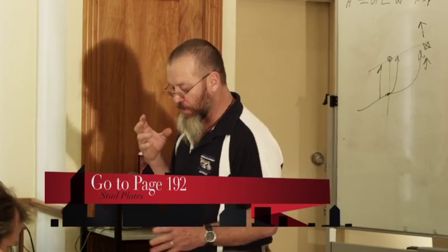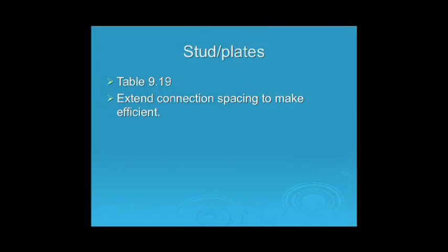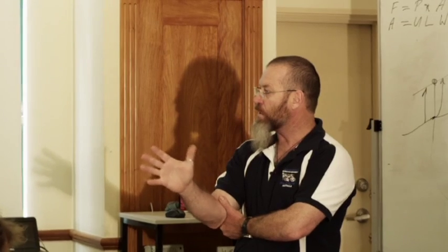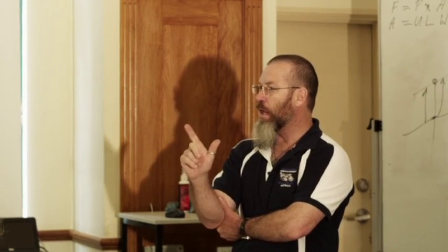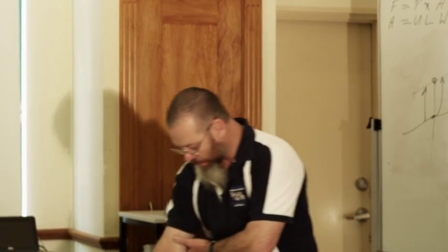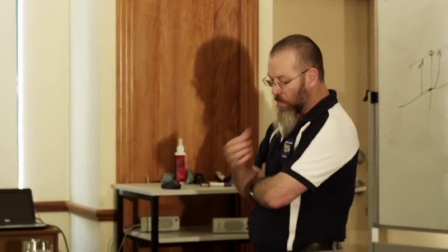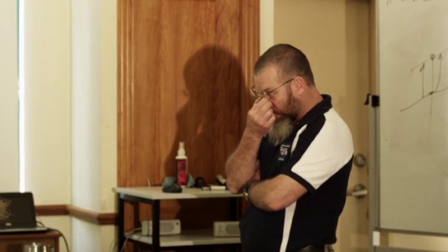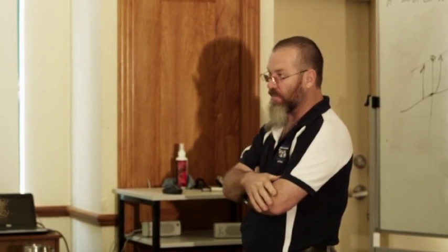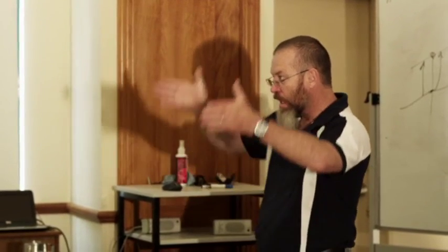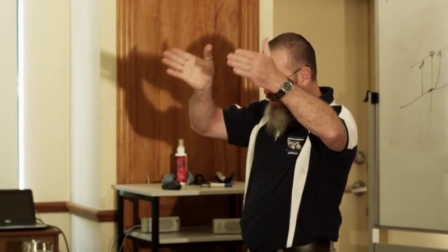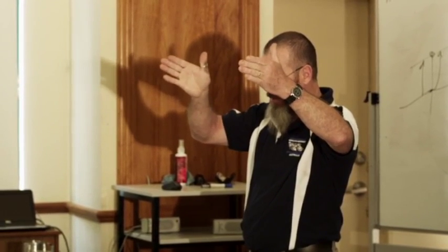Now we're talking about wall frame connections. We're talking about stud connections. Type D again is these stud straps over the top. Now, if you think about it, how far apart are those stud straps when your prefabricated frames and trusses come out? 1.8, 2.4 in most cases? The reason they're doing that is what they've actually calculated at that point is that they have a resistance, it might say a resistance of about 0.5 of a kilonewton, if you were to put those connections in every 600 millimetre centres at every stud. And that'd be stupid.